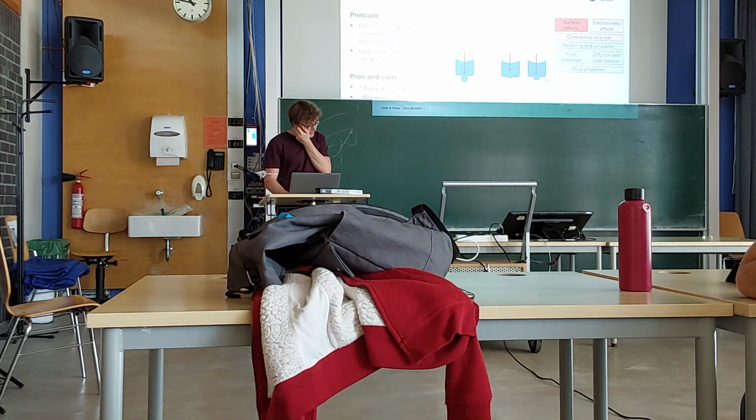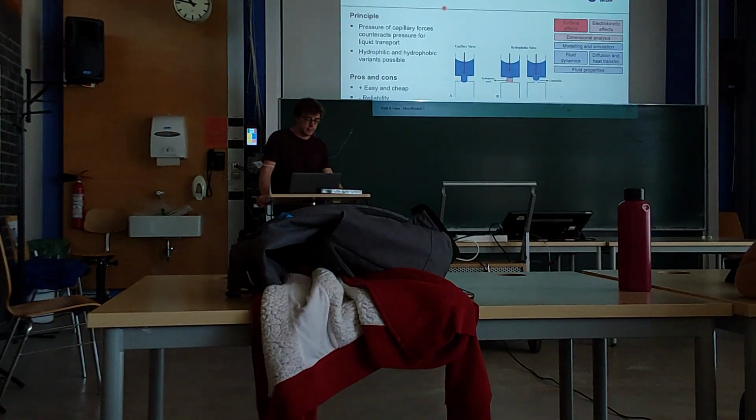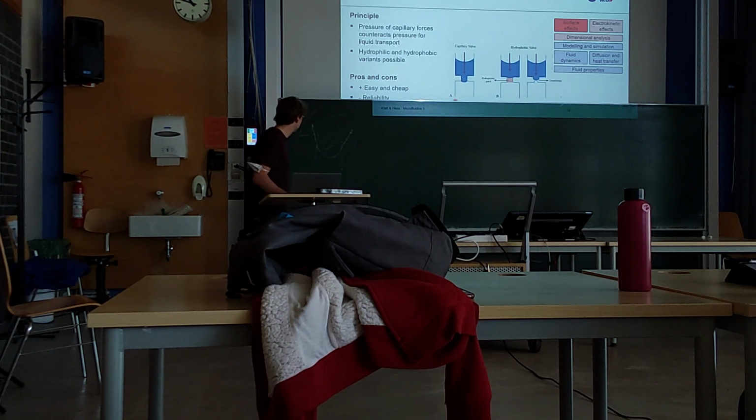And once again, when you make use of capillary forces, it's the easiest and most of the time cheapest approach to do what you want to do. The disadvantage is the reliability. As you can imagine, it's really important how big your channel is. If it gets bigger, your counter pressure will decrease. If it gets smaller, your pressure will increase. And this, combined with the buffer you're working with and the influence of the buffer, makes your capillary valve not very reliable.